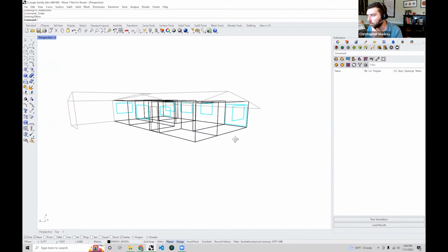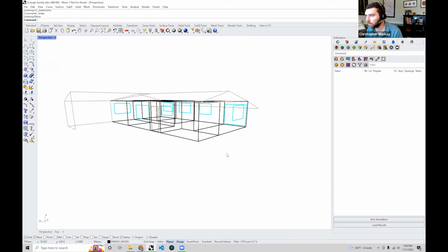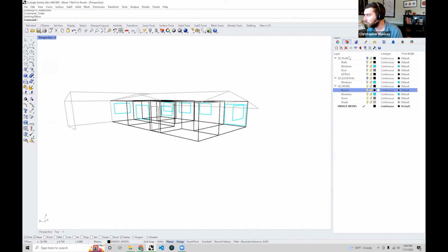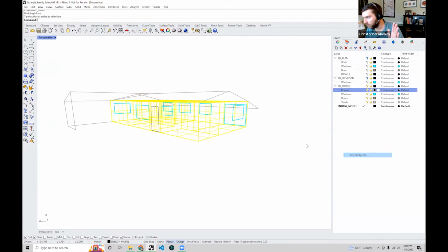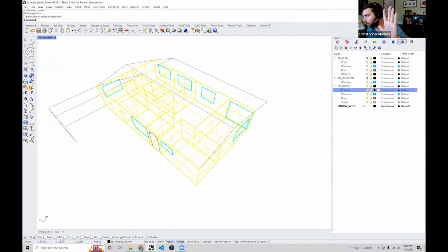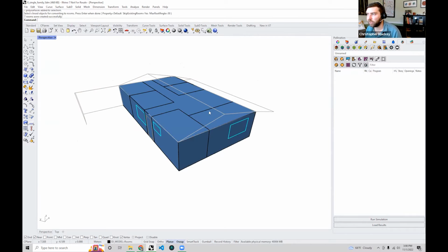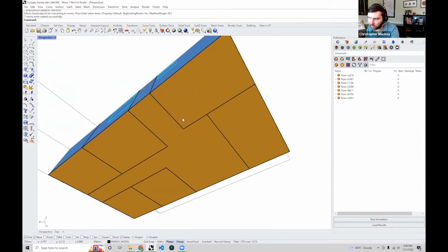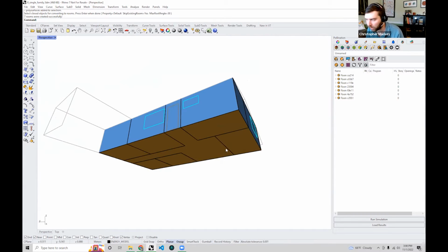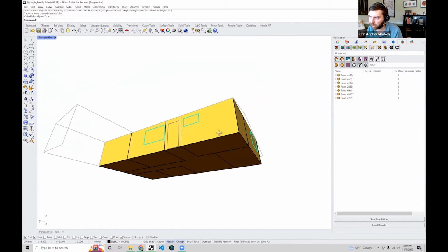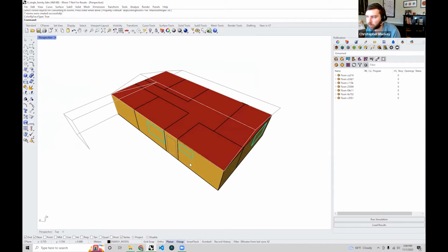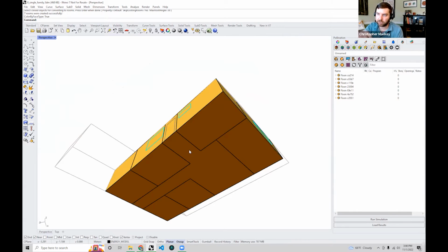Basically, there are default assumptions built into this when you create these rooms from these solid geometries. So if I go back, I'm going to use what I had by default. I was just moving this around to show you guys at least what those assumptions are. I'll select geometries and hit enter here. And so you see, it knew that this was a ground plane because it's just this floor surface that's below the Rhino origin. And the way that it figured out that this is a roof versus a wall versus a floor has to do with whatever direction the surface is pointing in.